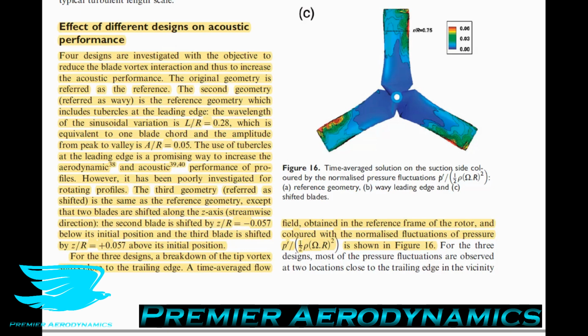The way that they work is very similar to a vortex generator, the difference being that vortex generators are typically located about 25% chord downstream of the leading edge, which means that this is where the vortices are being produced. Tubercles are on the leading edge, so you're getting vorticity being produced at this point and it's going over the entire wing. It's a slightly different topology going on, but often they achieve the same results.